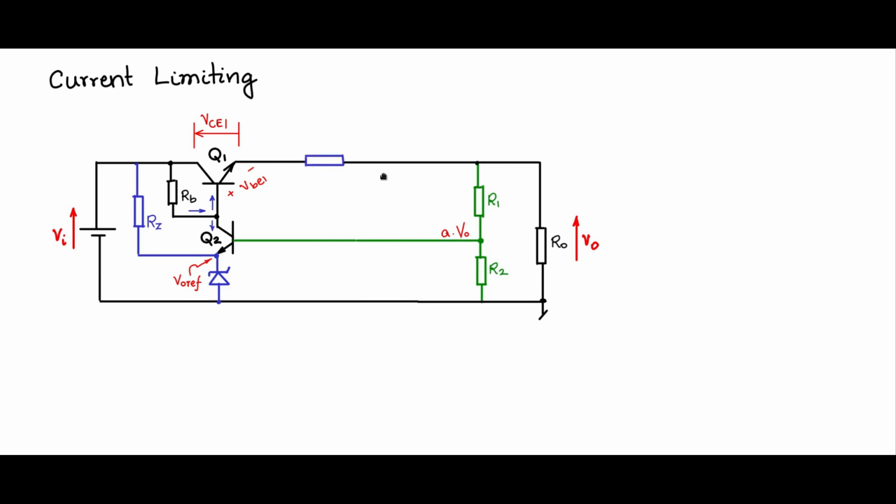and let me introduce a resistance in this fashion, and across the resistance let me connect the base emitter of a transistor, and the collector of the transistor is connected to this point. Let us call this transistor Q3, this is RS, and I0 flows here. You can say I0 is the current flowing here, approximately equal to I0, because the current flowing through this feedback tap point is very negligible.